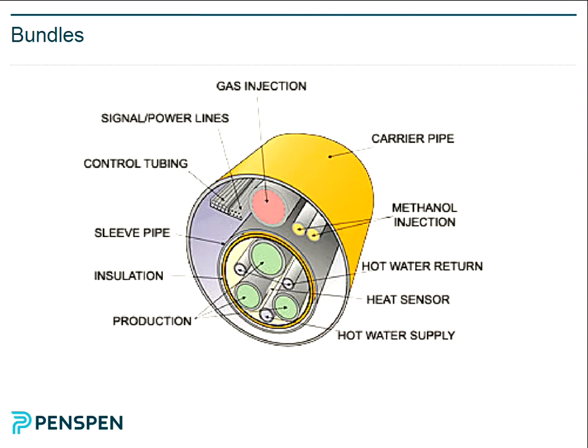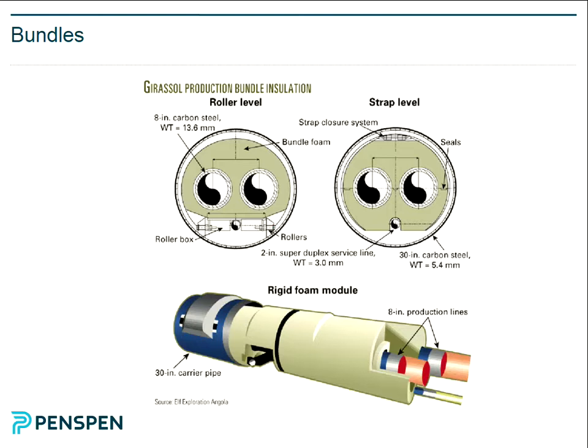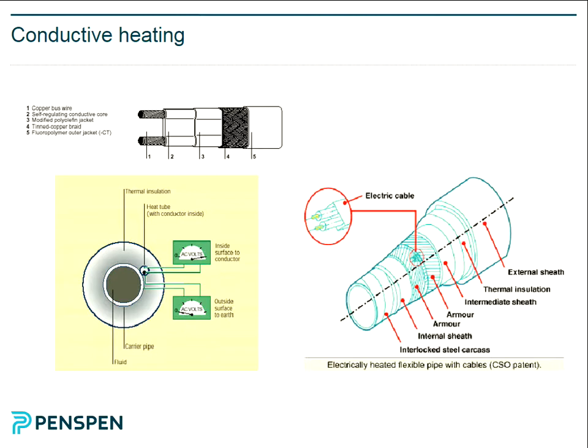For example, as that cools down, obviously hydrates might become an issue. So you'll find that the bits that are below the seabed will cool down much, much slower. So if you can have all your manifolds and pipes sloping, so if you shut down, all the liquid runs down into the below seabed parts, they will stay hotter for longer. So by careful design, you can mitigate potential risks from hydrates in a shutdown situation.